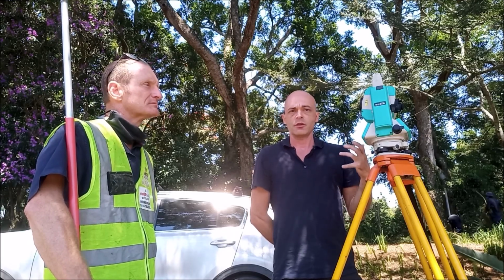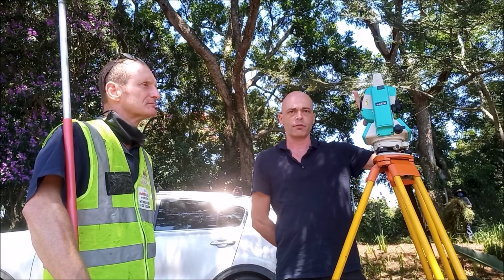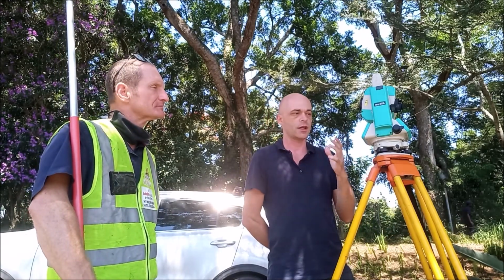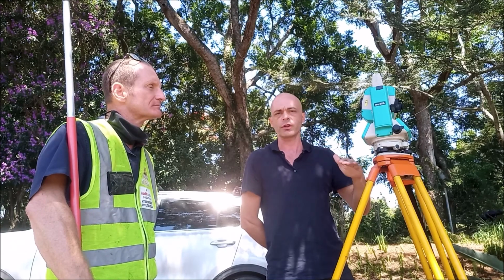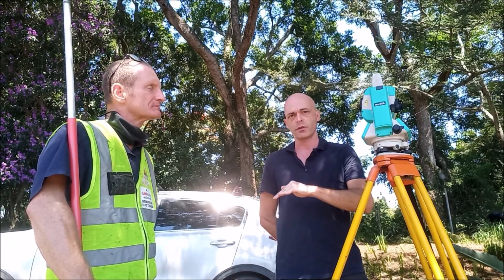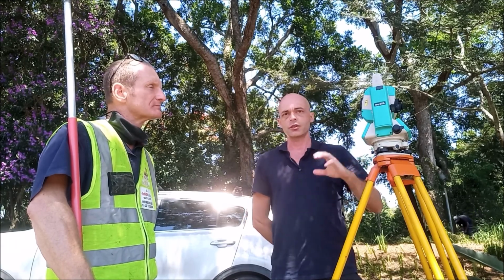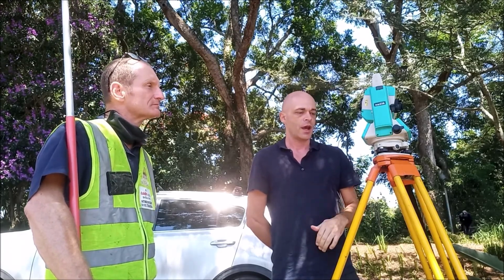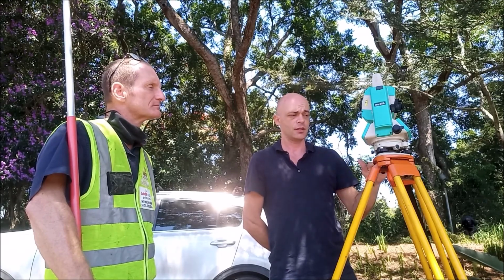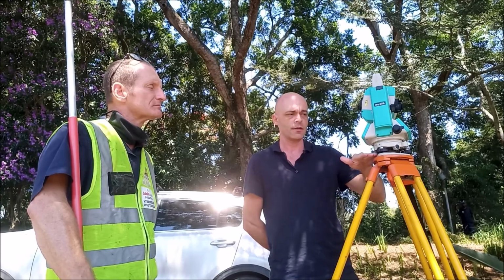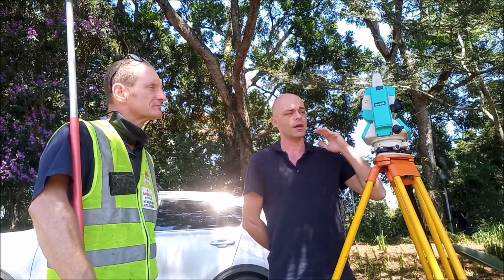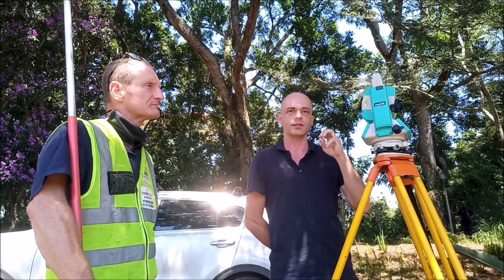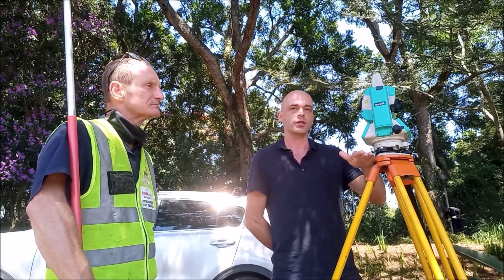Trigonometry can then be used because it's at a different angle depending on the angle of the prism being used, and with trigonometry you're able to identify the different distances that have been recorded. The important issue to take into account is that the height of the prism is fed into the total station to get that specific recording, because that is going to have some effect on the readings. The zero position, the base of this total station, is considered to be over here at the bottom of the total station. Some total stations have GPS units mounted on top of them, so you're able to identify exactly where that location is. So this is your zero homing position that you would then be measuring from.